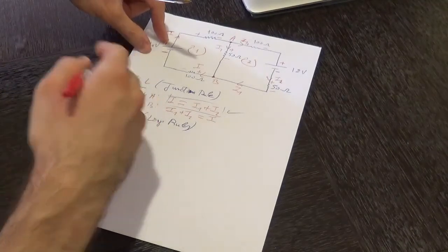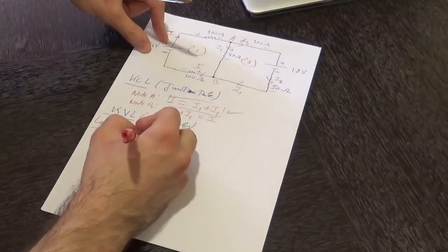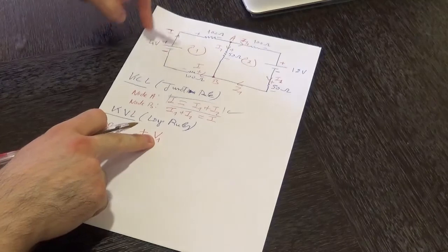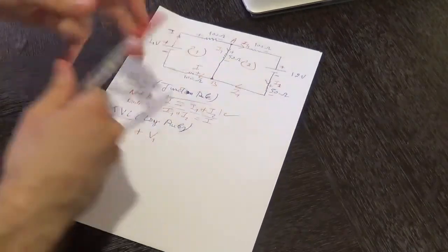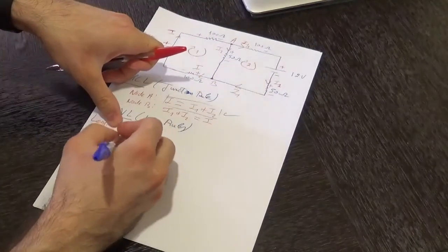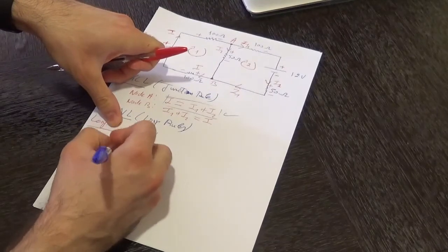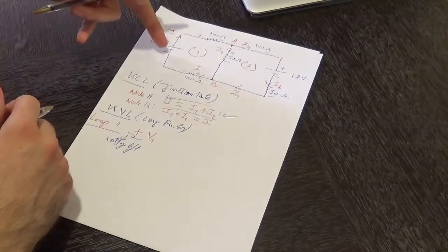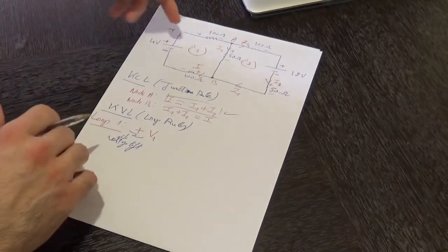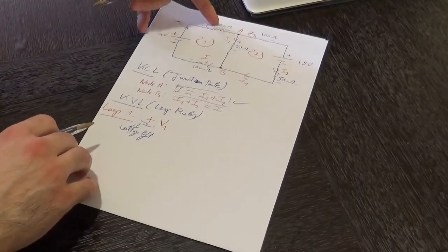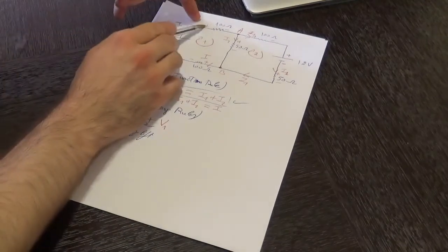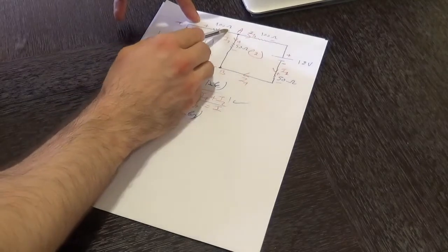So over here we have a voltage lift. We indicate that with plus V1, where V1 refers to the voltage of the battery. The plus sign implies a voltage lift or a voltage rise, meaning we are moving from a low voltage point to a high voltage point. Now arriving at that resistor, we are moving through it from a high voltage point to a low voltage point.